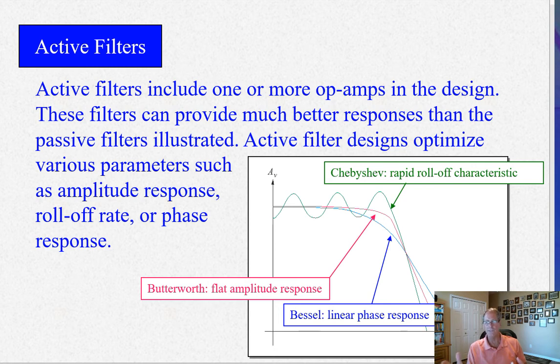It stays constant. Does that make sense? So at 100 kilohertz, you still have 90 degrees on the output versus the input. Not so with Butterworth or Chebyshev. You might have 90 degrees at 10 kilohertz and 120 degrees at 100 kilohertz. It changes.